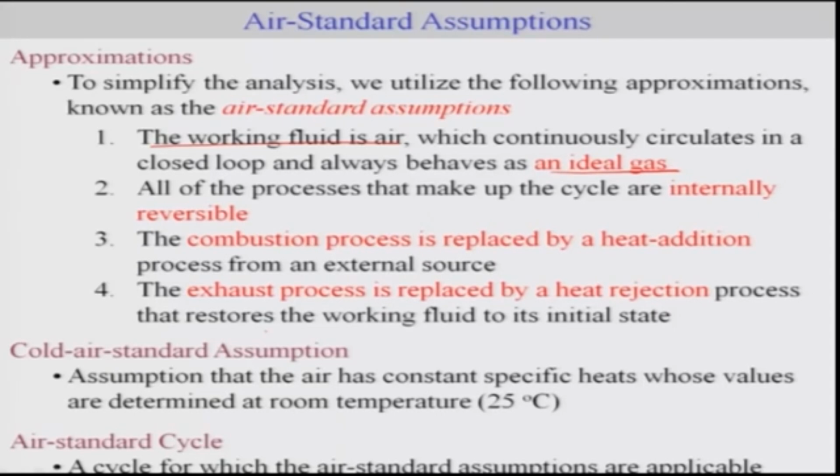All the processes that make up the cycle are internally reversible. The combustion process is replaced by a heat addition process from an external source, as I was mentioning in an earlier slide, and the exhaust process is replaced by a heat rejection process that restores the working fluid to its initial state.